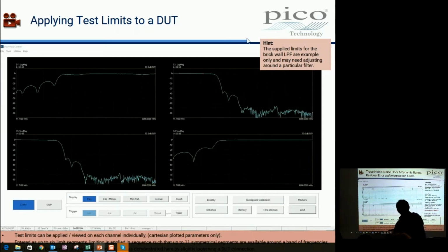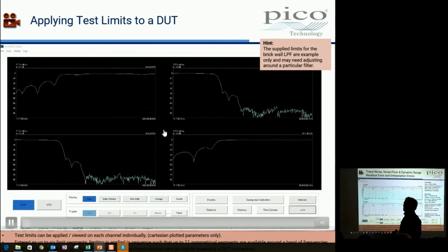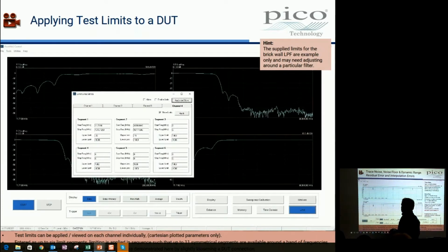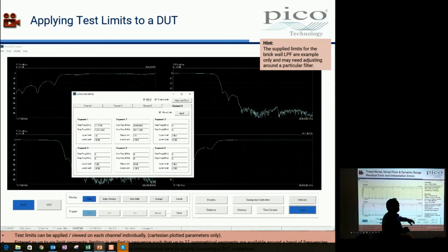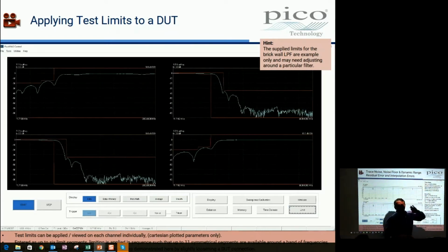You don't see the minimum as such on the log scale. So when we see trace noise, the peaks are going to be about 3 times bigger than the spec. Okay, so do be careful. You're not going to see necessarily this very low level when you look at it peak wise, you're going to see more.